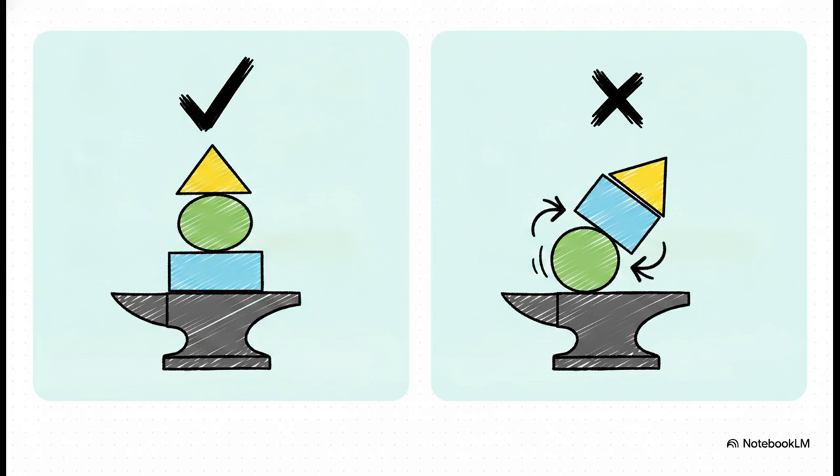So, why does that order matter so much? Well, if we have the exact same part, but we just swapped the primary and secondary datums in the callout, changing ABC to BAC, we've basically created a totally different set of instructions. The part is now physically fixtured against datum B first instead of A, which means a part that passes inspection under the first frame might completely fail under the second one just because of how it rests on the table.